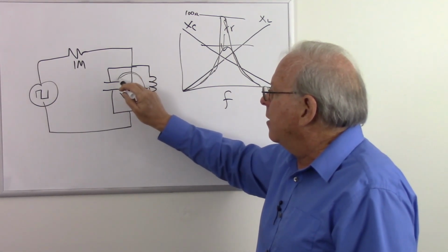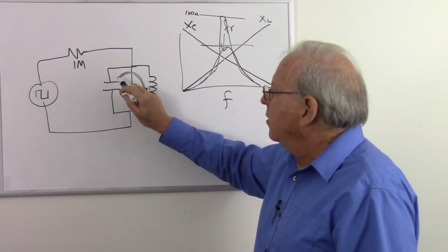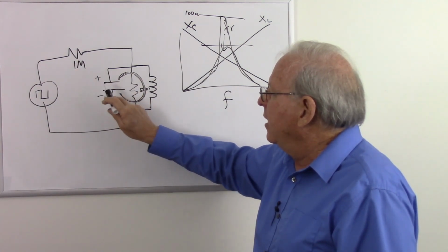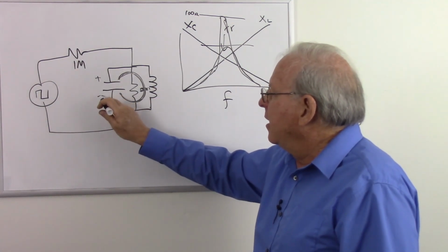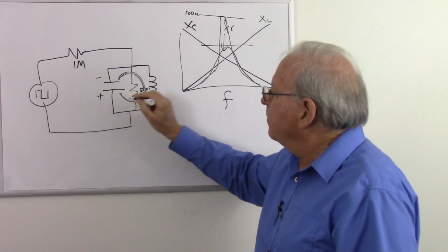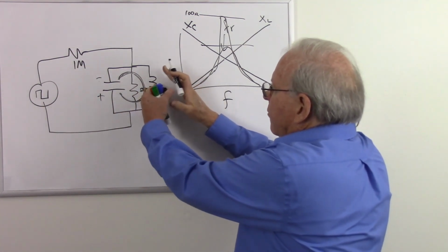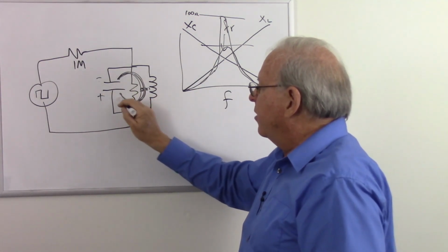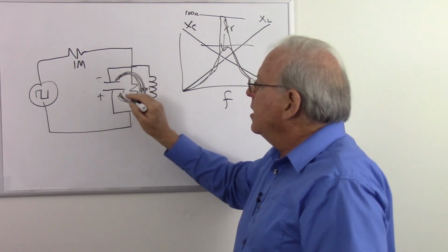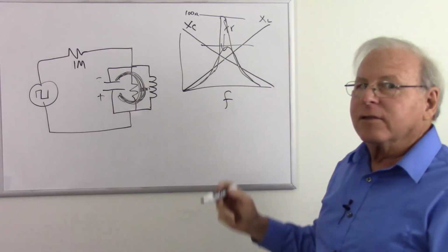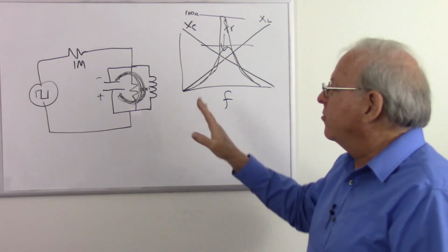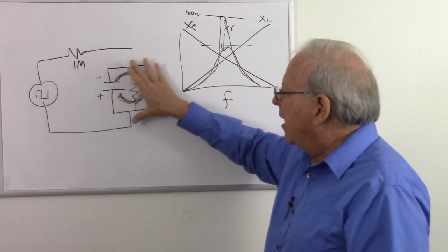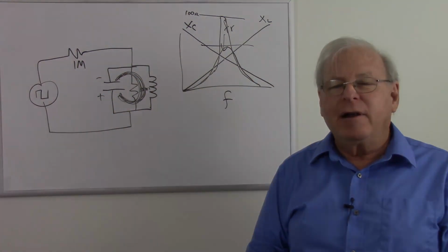But we put some resistance there and hit this with a voltage, it is going to transfer energy back and forth across that capacitor, so the voltage goes positive to negative, swings around negative to positive, and the magnetic field around the inductor builds and collapses, reverses polarity, builds and collapses, and that energy trades back and forth, creating a sine wave at the resonant frequency. So those are the basics of a circuit that has an inductor and a capacitor in parallel.